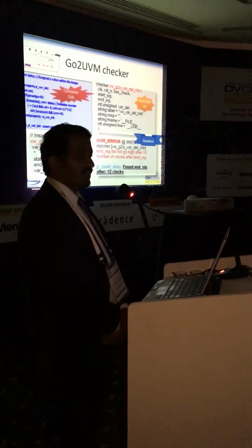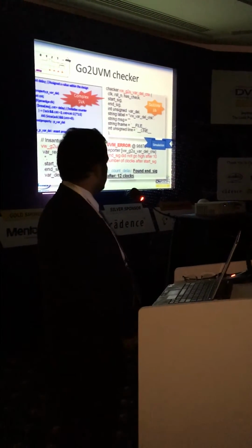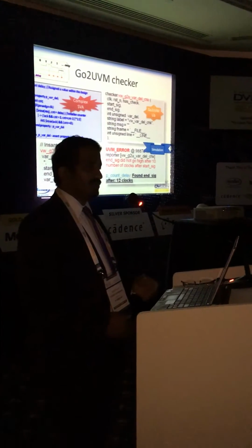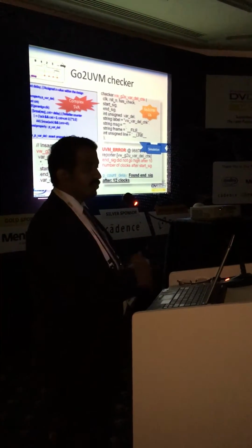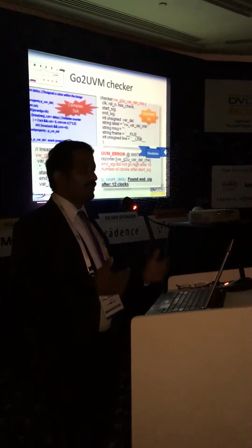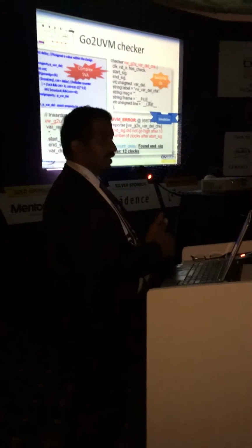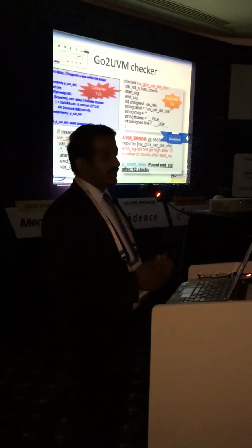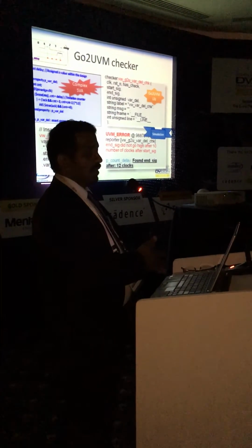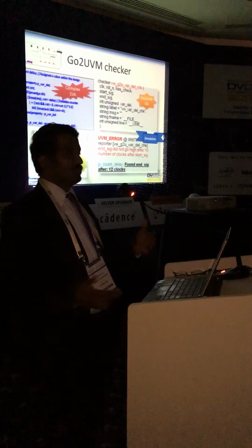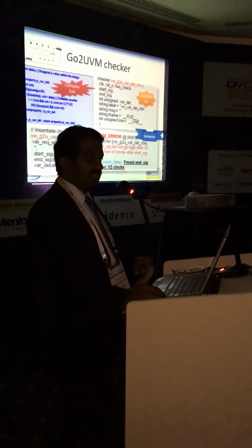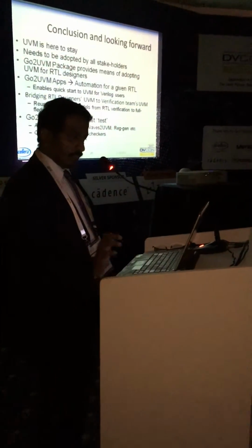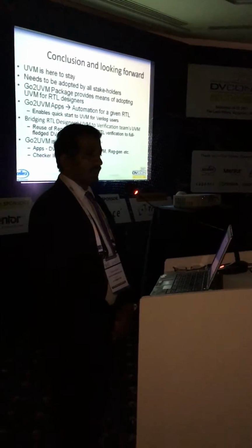What we also do, which is very nice, and some of our customers have given good feedback about this, is the last line. It also has a debug hook that goes in, and by default it is enabled. It says, look, you wanted 10 clocks, but I found the ACK in 12 clocks. So it doesn't do just a check, it actually does a little more. It does a count and then tells you, you were maybe looking at 10, but I got this end signal at 12. Of course, assuming the design did toggle the ACK. So there are two things built into the checker library. One is the check itself, the bunch of assertions, as well as some debug code that tells you what's going on there. Okay, so that's my last slide.